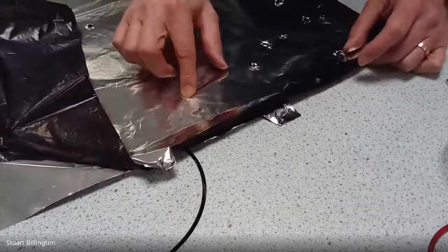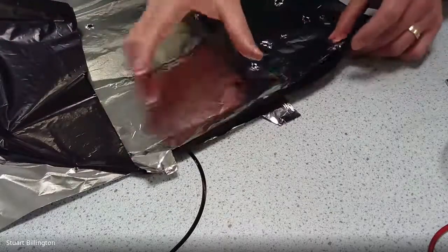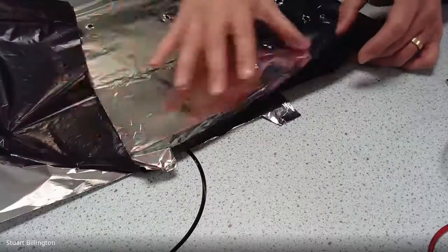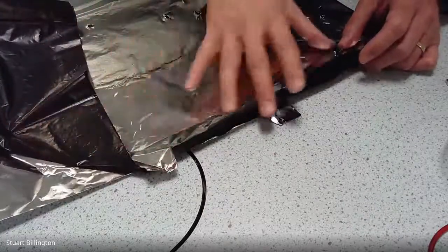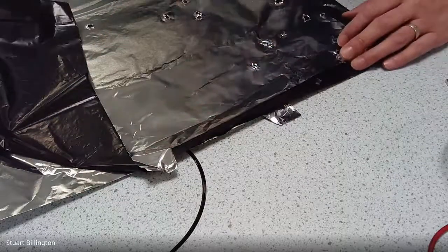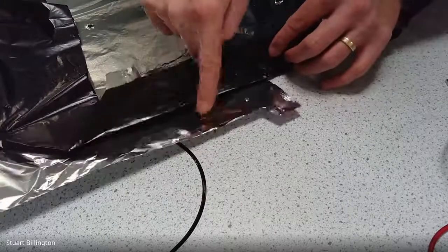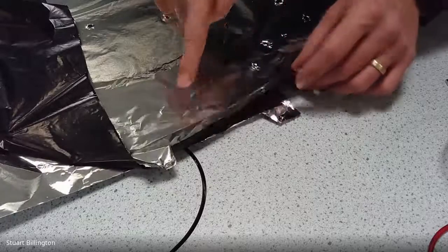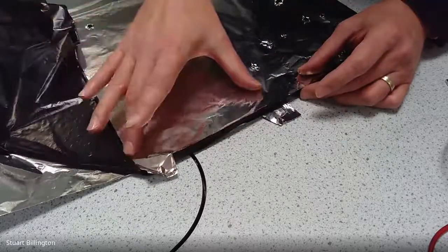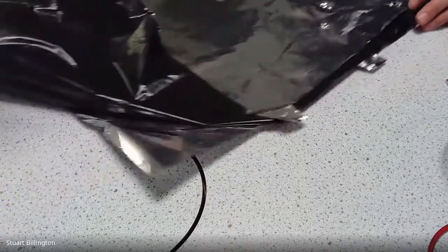And so what we find is that if we try to arrange the plates so that they don't overlap, the charge just arranges itself on the overlapping area, and you don't really get much charge on the non-overlapping area. Therefore, it's not as simple to say, what's the area of the conductor? What we actually need to talk about is what's the area of overlap between the two plates. It's this area here that's actually the important one, not the actual physical area.